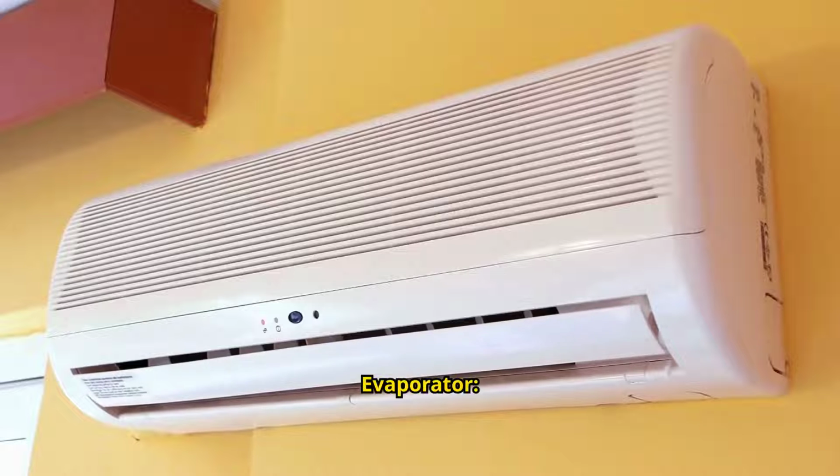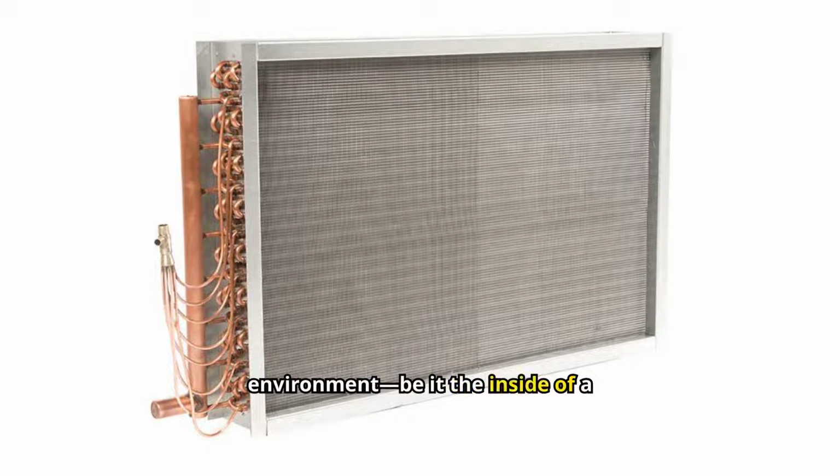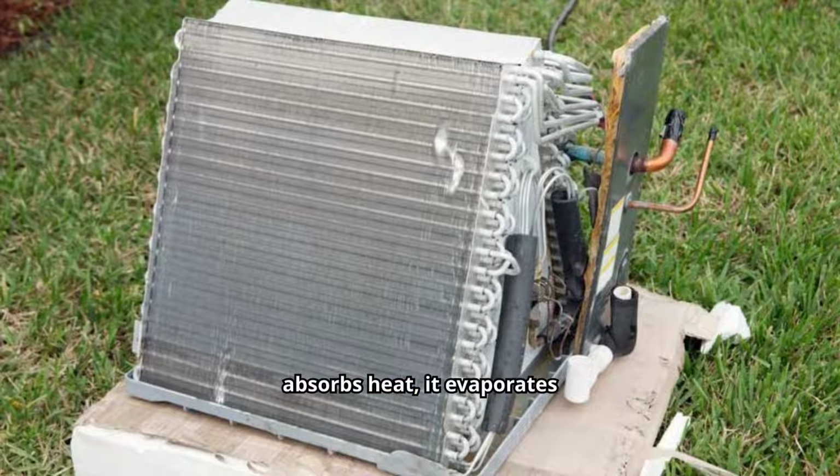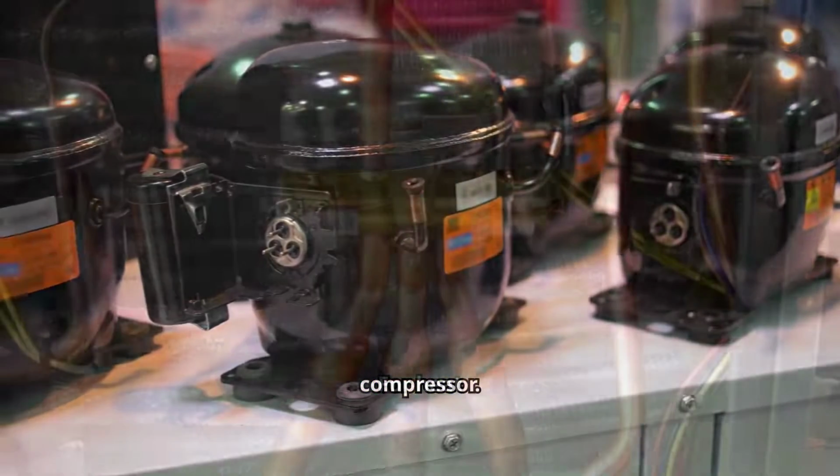4. Evaporator. In the evaporator, another heat exchanger, the cold refrigerant absorbs heat from the environment, be it the inside of a refrigerator or the air in a room. As the refrigerant absorbs heat, it evaporates into a low-pressure gas. The cycle then begins again as the gas returns to the compressor.